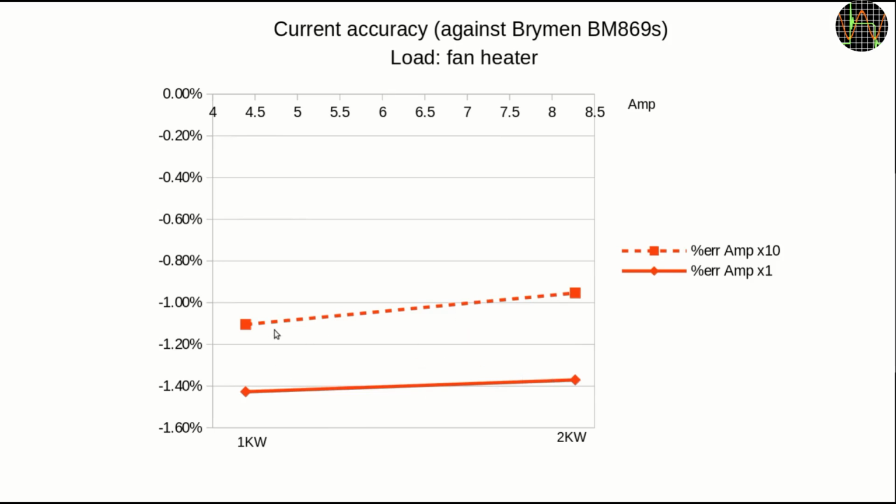In ×10 mode, the 8 amps is actually measured as 80 amps, so we are covering almost the complete range of a 100 amps current transformer. In any case, it appears that adding the ×10 mode is definitely a good idea, but I would like to caution that you should avoid switching between ×1 and ×10 under load, as this generates a huge spike, which is sometimes enough to disrupt the communication on the serial interface.